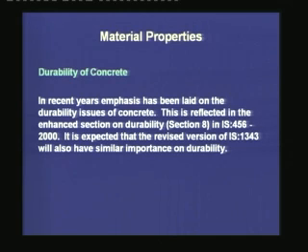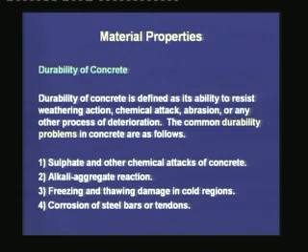Now, in recent years, emphasis has been laid on the durability issues, and this is reflected in the enhanced section on durability in IS 456-2000. It is also expected that the revised version of IS 1343 will have similar importance on durability. Now, the durability of concrete is defined as its ability to resist weathering action, chemical attack, abrasion, or any other process of deterioration.